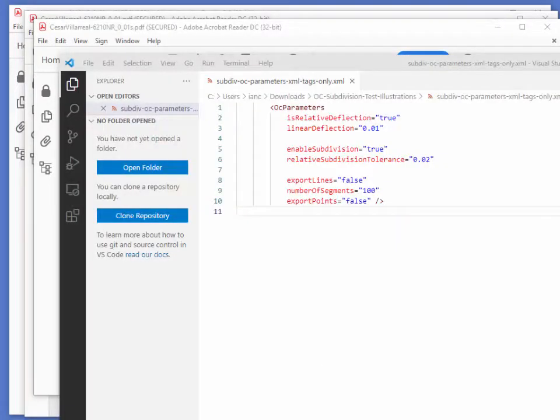We've been showing here step conversions to 3D PDF. The parameters for controlling this, first of all, have the linear deflection parameter, which can be enabled and set to a value appropriate for your model and the type of curves that you're trying to represent. And those are available in XML control parameters through the PDF3D IO SDK. And then further, the new subdivision system that we've added also has an enable and a separate subdivision tolerance that can be applied for the planar surfaces.